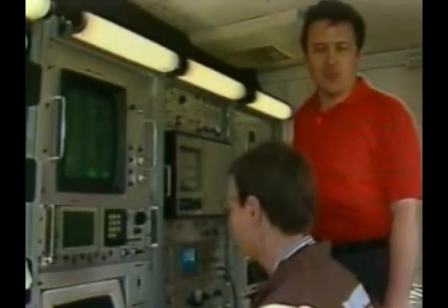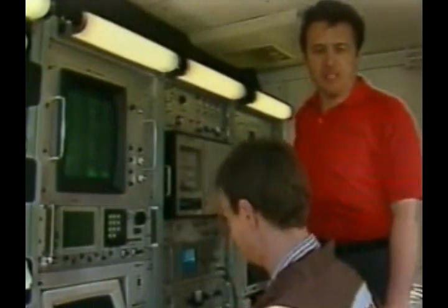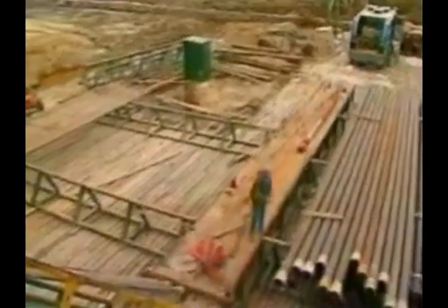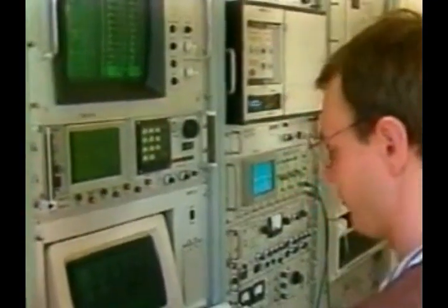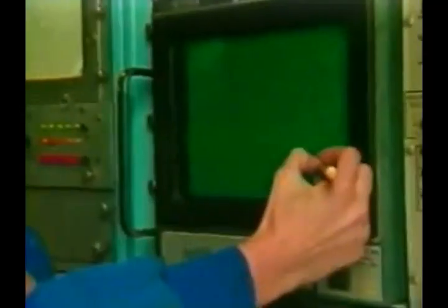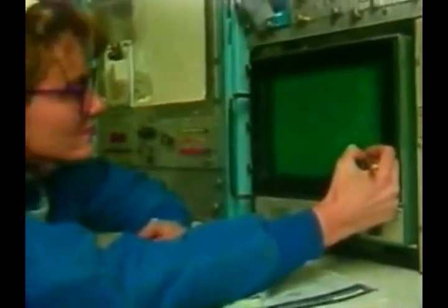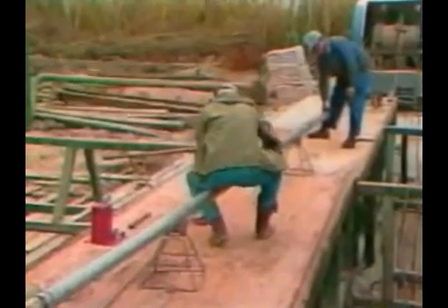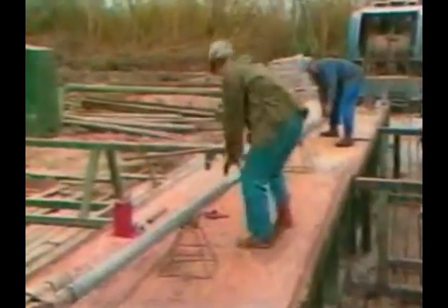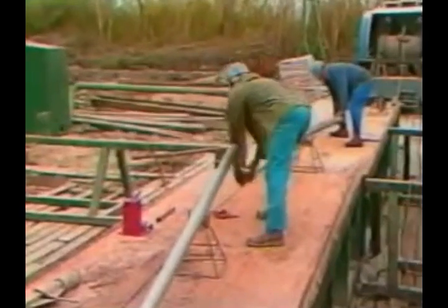An open-hole logging survey can be thought of as consisting of 3 phases. The first phase includes mobilization of the logging unit, on-site rigging up, and field calibration of logging devices. The second phase is the logging phase, during which tools are run and the system is adjusted to hole conditions and previous logging runs. Logging measurements are taken during this time. The third and final phase concludes the survey and comprises on-site after-logging calibration and rigging down. The preparation of the field prints and well site interpretations must also be completed.